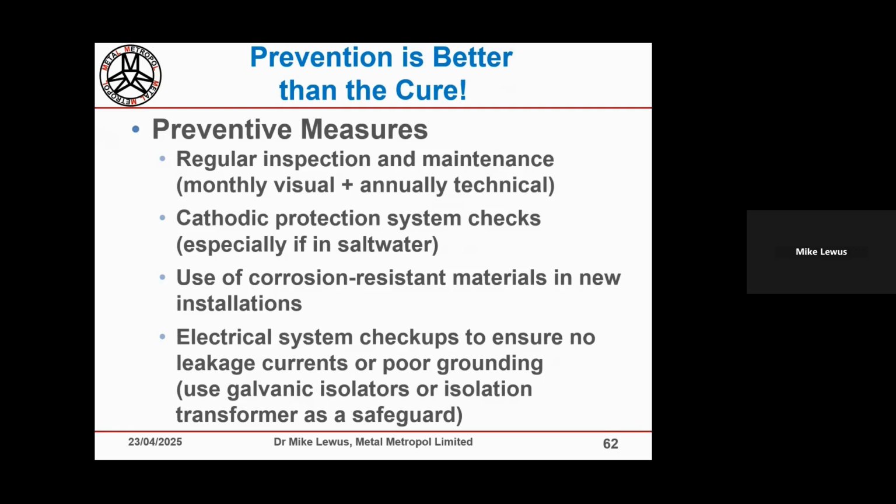Brackish water, it's usually aluminium, but there's more of both aluminium and zinc anodes used in seawater. But in fresh water, the normal approach is to use magnesium anodes just because of that reason, because it gives a higher driving voltage. So on that 40-footer, how many would you put on, and what sort of size?